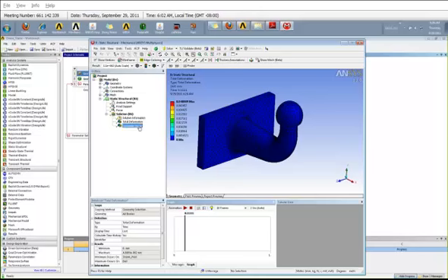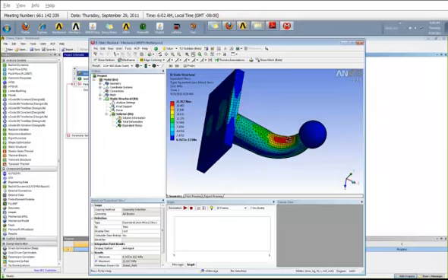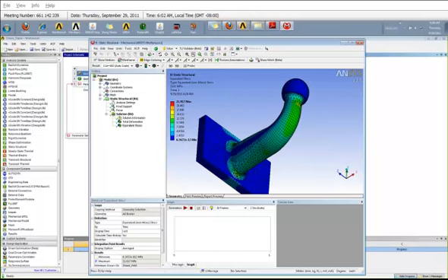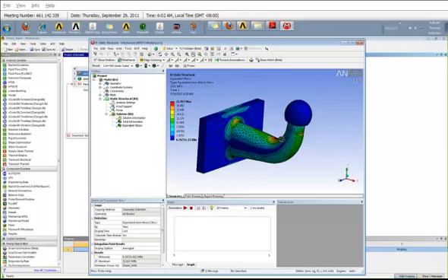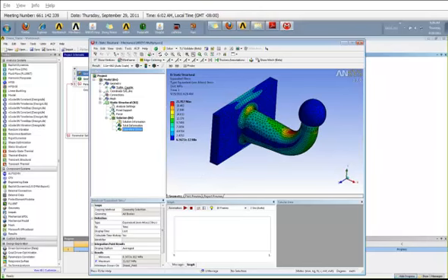So the force is stretching the trailer coupling. Also, I can look at my equivalent stresses here. So the maximum stresses develop around this neck region over there, and also the stresses develop near the fillet region over here, and the top and bottom of the fillets, and also some stresses are developing in the elbow region also. So the material that I used is